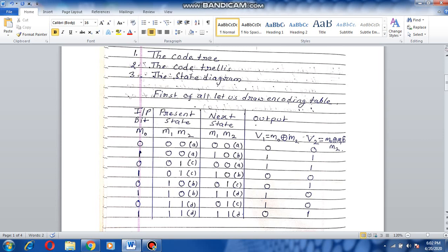As the input enters into the coder, after one bit shifting in the right direction, the elements that are stored in M1 and M2 will be termed as the next state. So we are considering both the possibilities of input bit as 0 or 1, and as the state is of 2 bits, we are considering all four combinations 0 0, 0 1, 1 0 and 1 1.